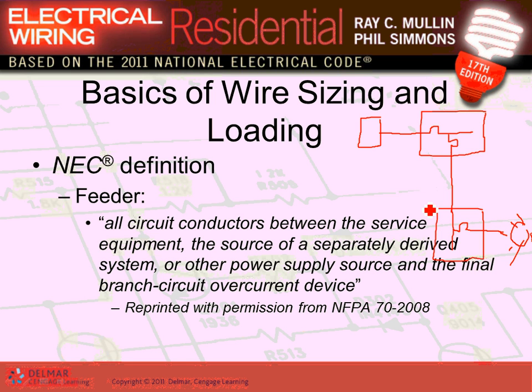So what you're dealing with is this right here, called my branch circuit. Right? Branch circuit, right in here, between the light and the 20 amp circuit breaker. Now, this is a 100 amp circuit breaker. Between the 100 amp circuit breaker and the panel here, that's my feeder, Mr. Feeder. And this is my 400 amp panel coming in. And that conductor coming from the transformer, XFR, is my service entrance conductor circuit.